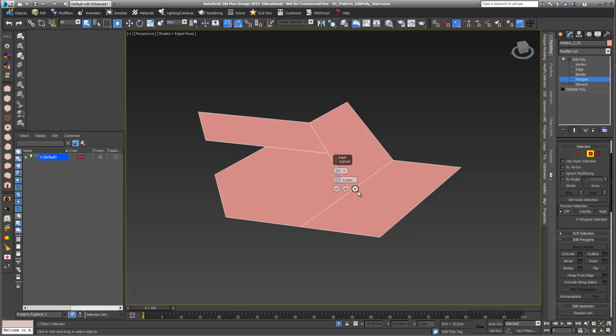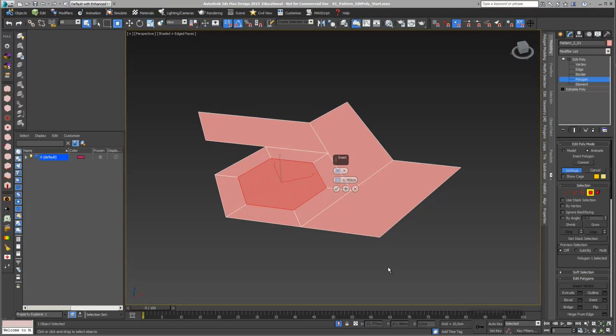I go into my settings, and you can make an inset if you choose this, for example, like an inset with this polygon. Okay, and I just close this and just press OK, and the next thing I go again and just rename it like edit poly number 1. I gave it the name, and I just say the whole thing is inset.